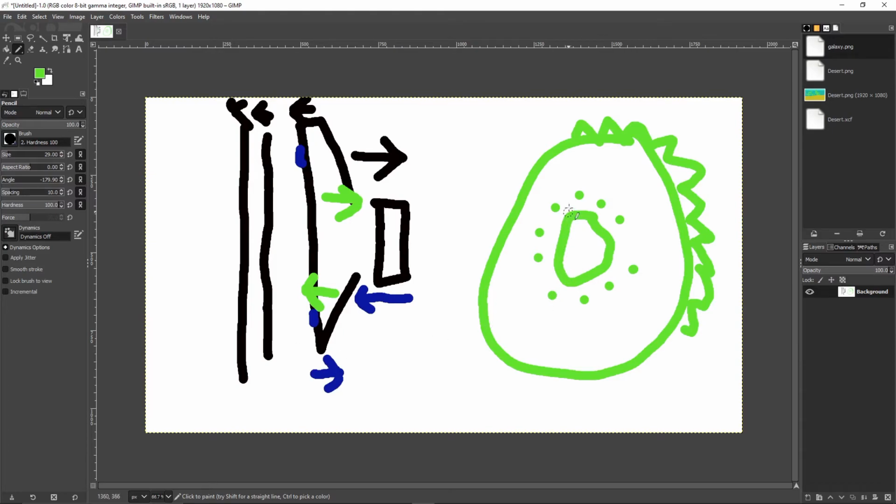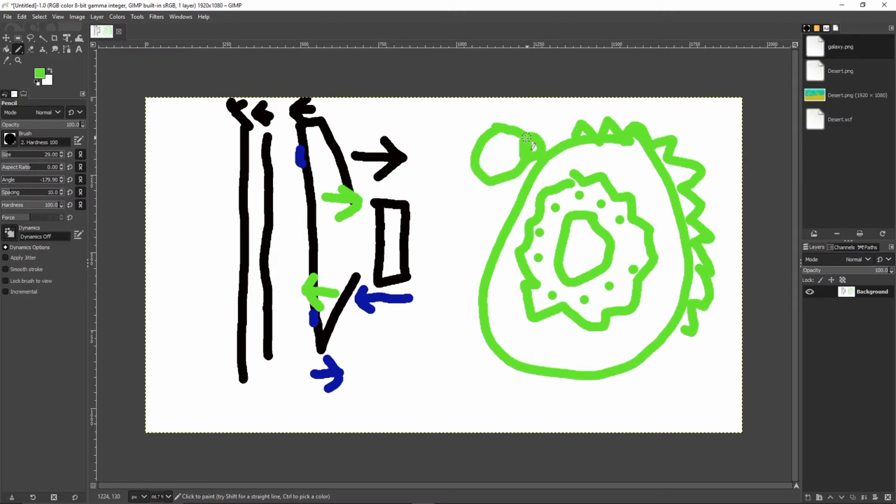inside bolts, okay? And it will crack. It'll get a spider crack like this. And I've seen this. We get one of these once a month on that Reddit, where it'll get a crack. So now the starter lives here and has a little gear that comes out to grab these teeth, right? So the starter is spinning the flex plate or the flywheel, but because it's cracked and broken, the inner circle here that is attached to the crankshaft isn't spinning. So I've seen this a couple of times where I can hear the starter is turning and something is spinning, but the engine is not starting. And that's 100% this guy right here.